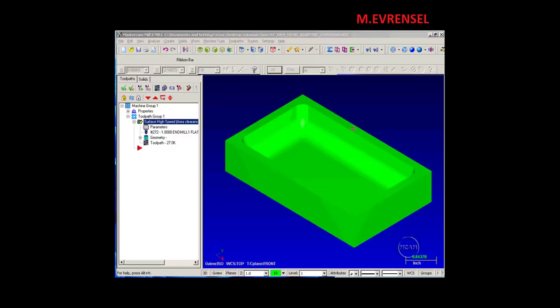For the tool paths that use constant Z cutting, those are core roughing, area clearance, and waterline finish. We have the ability now with surface high-speed machining to use adaptive step-down. Those constant Z cutting tool paths tend to work very well in steeper portions of your part, as 30 to 90 degree walls. However, when you get into more shallow areas, they tend to leave very large stair steps.